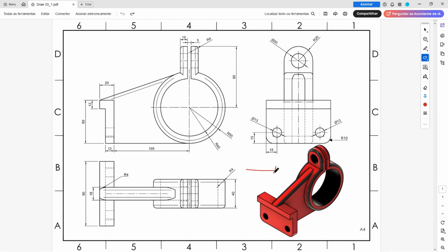The first step to create this part, we will select the right plane and make this sketch. And here will be the midpoint. The first thing that we make, we will create this profile here. We will create this first to avoid some fillet errors, okay? So this arc here has 50 millimeters of radius, and we will make this sketch and put the dimensions later,